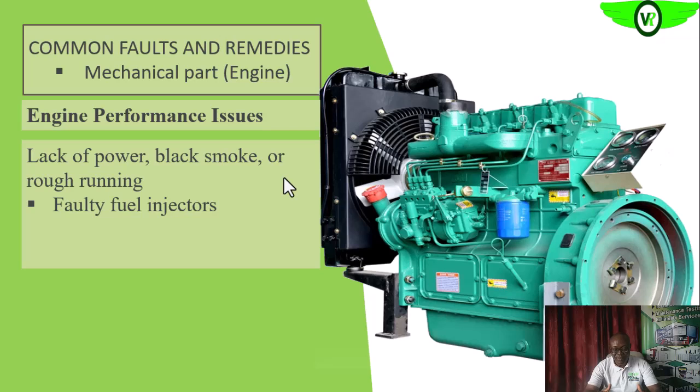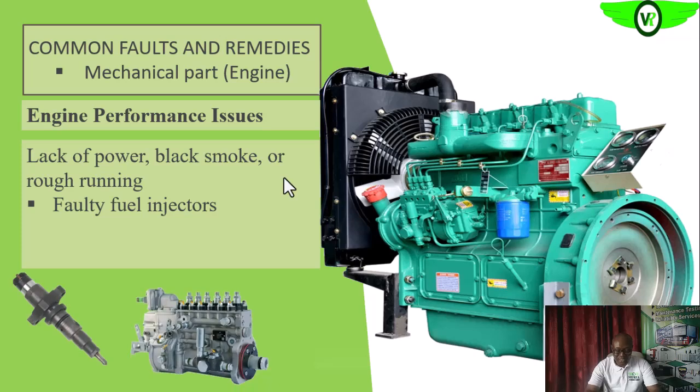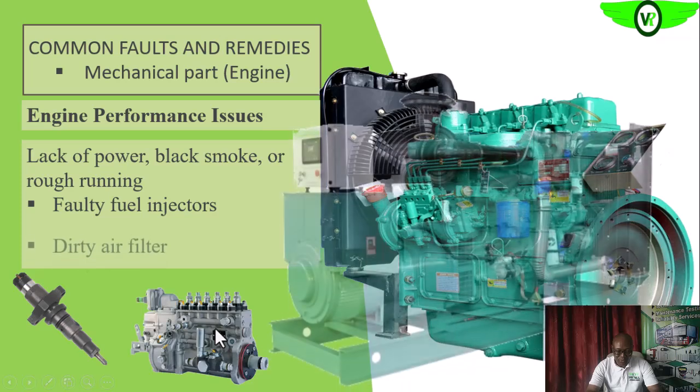and can generate black smoke. You see carbon in the exhaust gases. Okay, a lot of carbon. So that tells you that you have a problem with the injection system. Okay, especially the nozzles. So here we have the nozzle and the injection pump.